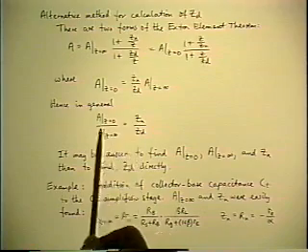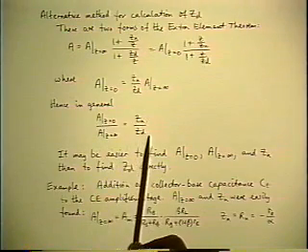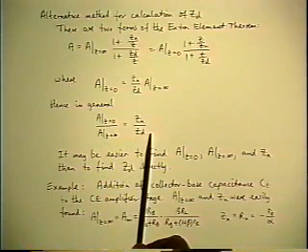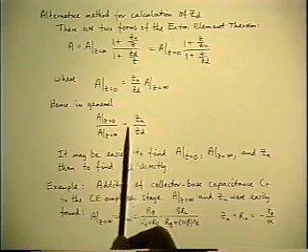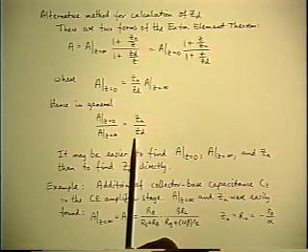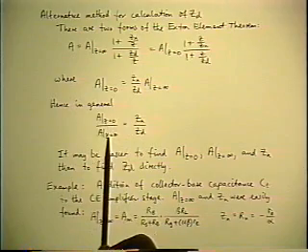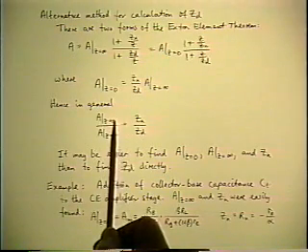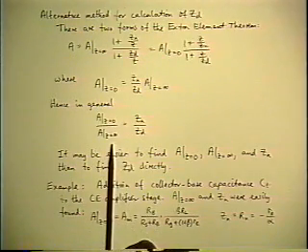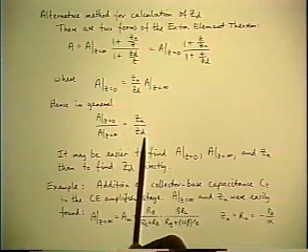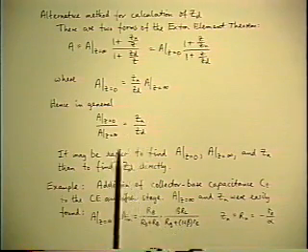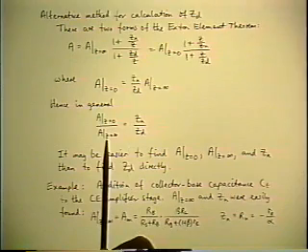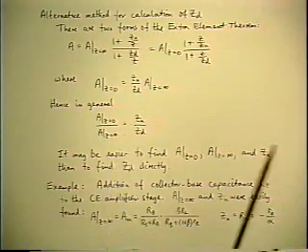The ratio of the two flat gains is equal to the ratio of the corner frequencies that separate them. This is the same thing where the variable is impedance. So the ratio of the gain of the system when the element is zero to the gain when the same element is infinite is the ratio of the two driving point impedances seen by that element. It's sort of a redundancy relationship.